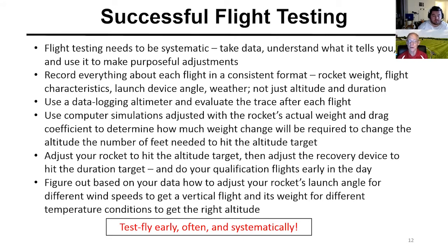And you need to figure out, based on your data and your experience in various weather conditions, how to adjust your launch angle for different wind speeds, because you can't control the wind speed of the day on the day that you have to do your finals flight or even your qualification flight. You can pick to not do a qualification flight on a really windy day, maybe, if you don't run out of time first. But you need to know what you're doing and pay attention to that launch angle